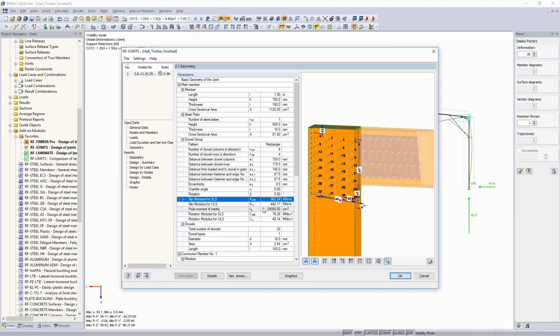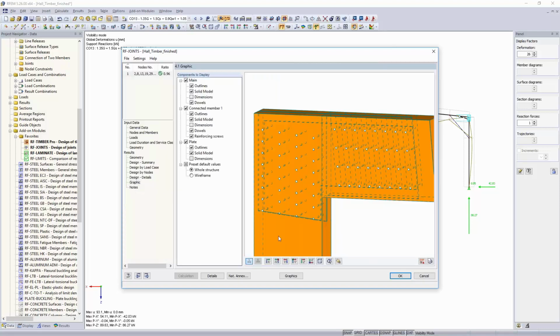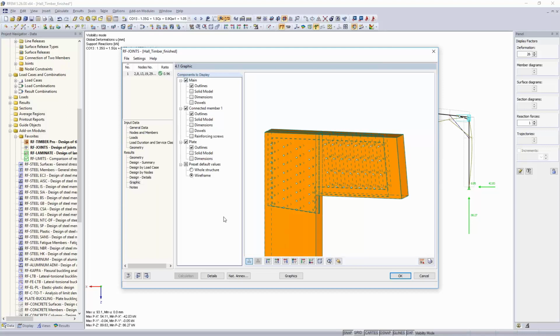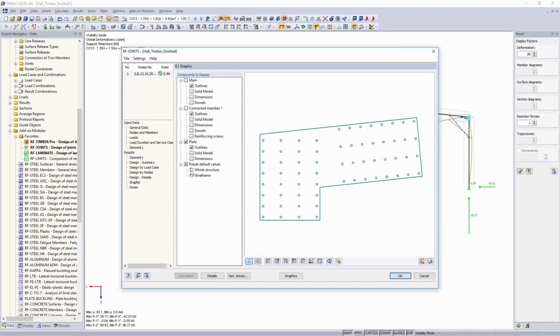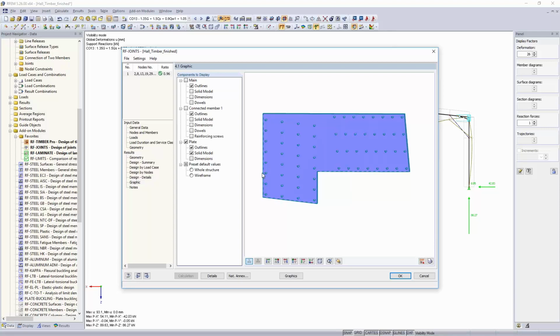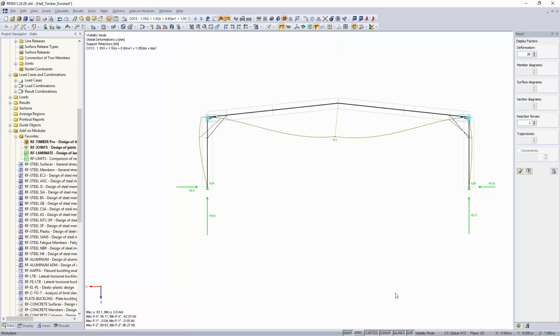It does it similarly or differently for SLS and ULS situations. It's the same equation 2.1 according to Eurocode 5, and it exports that differently for every load combination. You can also export a DXF or a plot, maybe when you just want to export the plate to something. You can also export to your CNC and create a shop drawing of it as well. Okay, yes, we can check connections also for fire. I said it when I introduced it, but with a simplified approach.